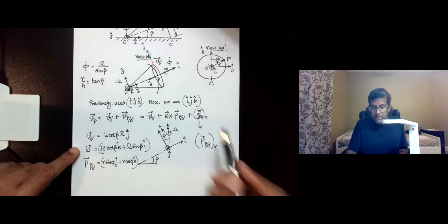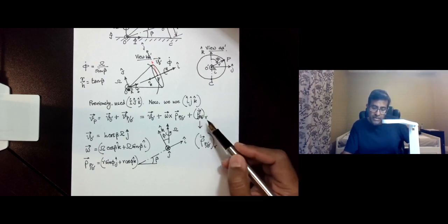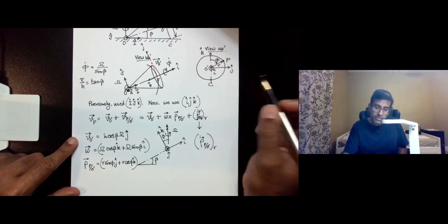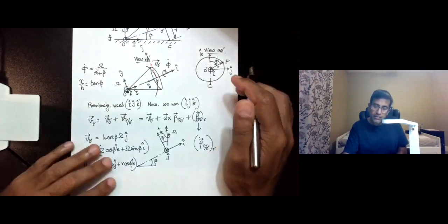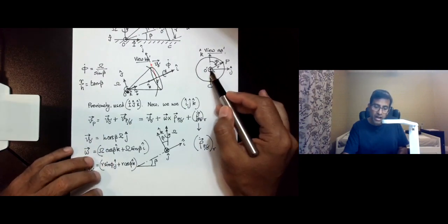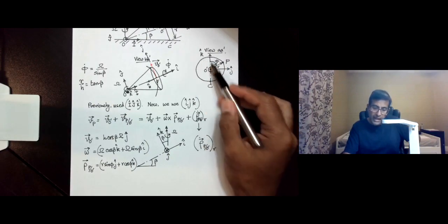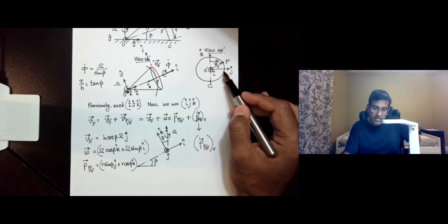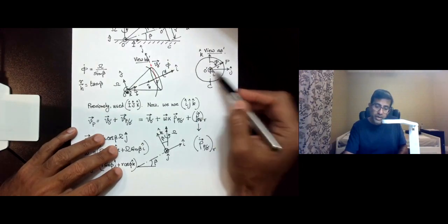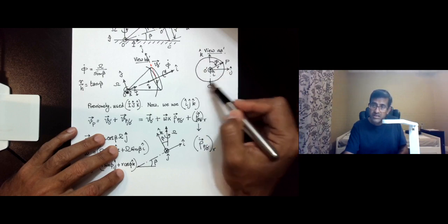Now to find this vector, we first get an understanding of what this vector means. This is the velocity of the point P within this rotating frame. So imagine that you are in this rotating frame. What velocity would you perceive the point P to have? So imagine this I, j and k that is on the face of this base circle, and they are maintaining their direction, that they are of course rotating with the rolling cone. But with respect to this I, j and k, the movement of the point P is going to be just the spinning motion.